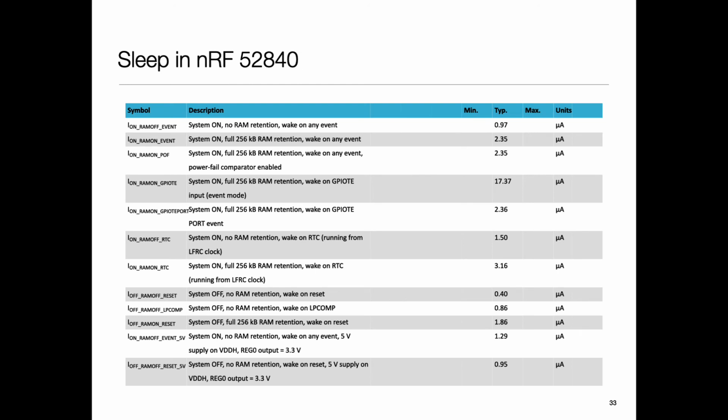There is a pretty elaborate structure of sleep. We think of it like, oh, I put the processor to sleep, but there are many different modes and different implications. When you come out of sleep, what was remembered and what was lost? Before I go to sleep, I have some state, right? Some settings, some data. If I'm willing to forget all of it, then the task of going to sleep and waking back up again is easy. If on the other hand I have to preserve it, that's where the hard thing comes in. So a lot of these things revolve around what it is that I'm putting to sleep and what it is that I'm willing to forget.